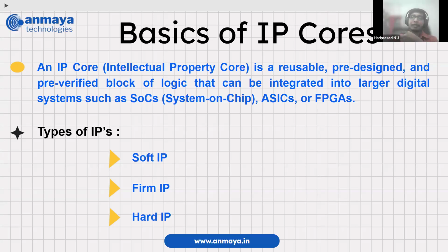Whereas in the soft IP, we are going to utilize the existing resources, and one part of your IP may be placed in one corner of the FPGA when placement and routing is happening, and other components may be placed somewhere else. So your critical path may be different, and your delay is not actually calibrated. So it is slower. The Fmax that you can achieve is limited.